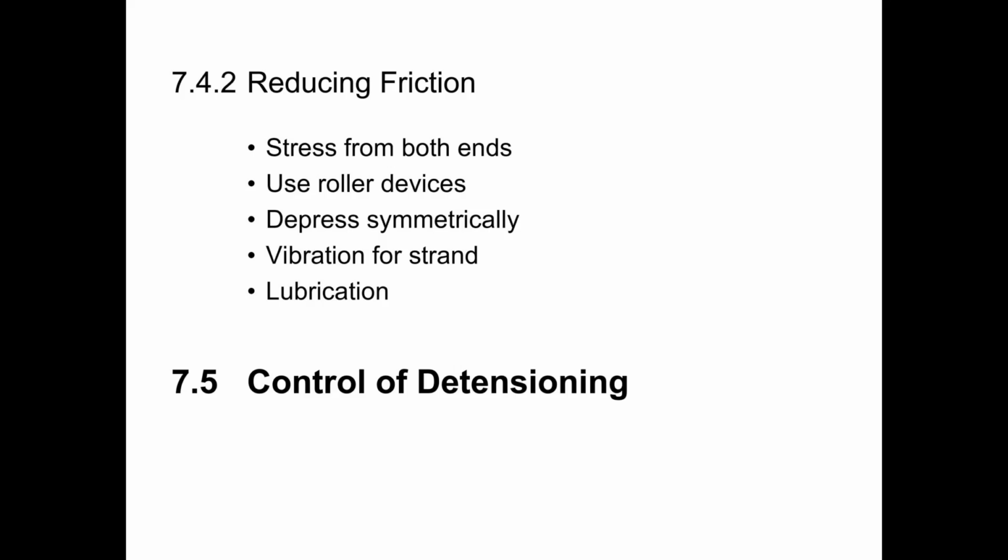We've also talked about depressing the strands symmetrically if they're tensioned initially in the straight position. Then when we go through our depressing sequence, we want to do that in a symmetrical pattern.